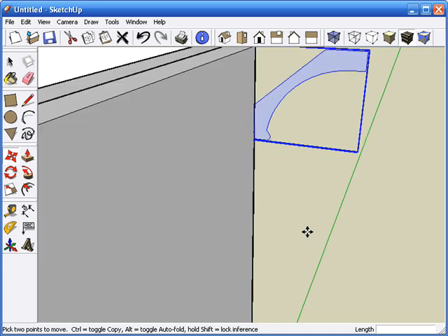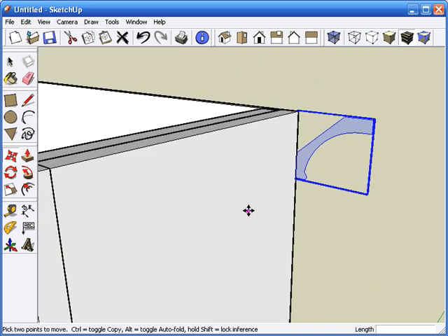So now we've got our crown molding there, and let's do a little math. Let's measure how far down that crown comes. We'll use the scale tool here, the little tape measure, and we'll put the dot right at the top and slide it down until the pink dot shows up at the bottom. And look at the little window there, it says 2 5/8. Let's make a click right there, and that'll set a point there.